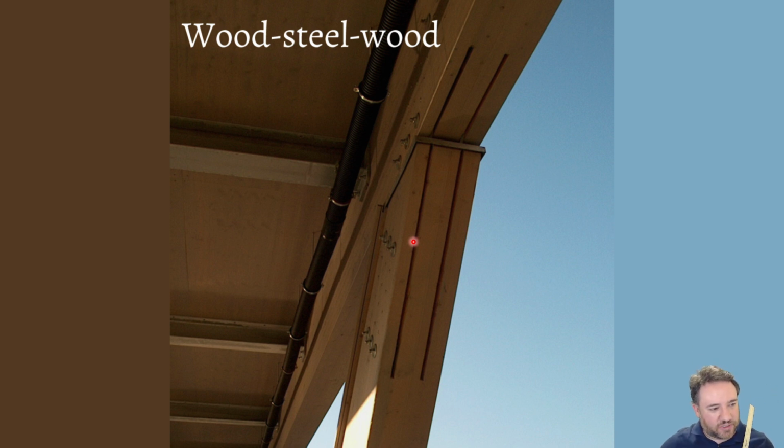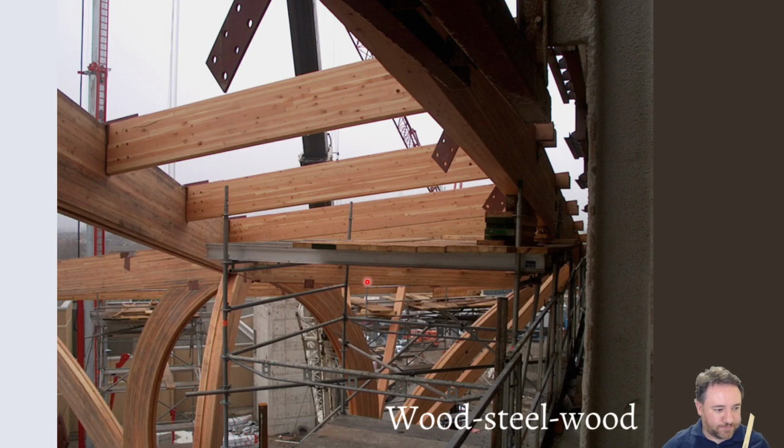Here we basically would design this as 2 separate wood-steel-wood connections. I'd have the one on the left, wood, steel, wood. Then I have the one on the right, wood, steel, wood. It tells you how to design that in the standard. The nice thing about this connection is it's nice and hidden. So you don't actually see the steel plates, except for this one here that joins them together. So it's a very attractive type of connection. And you can see that the steel plate is held in using bolts. In this case, the bolts aren't all installed yet. You can see there are some holes. This is an under construction picture.